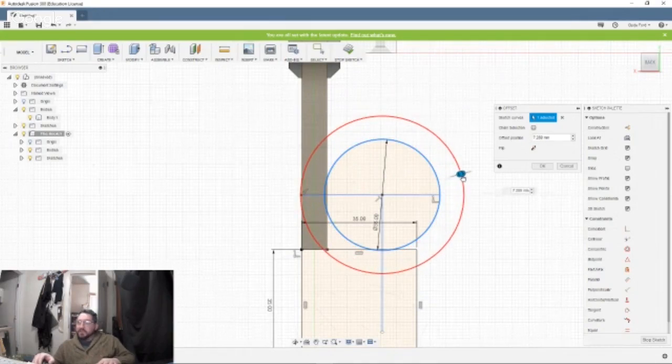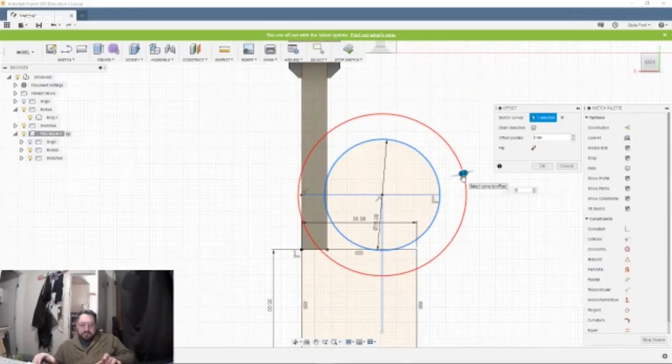I'm still learning how to use this program, and it's fantastic. I'm pretty much self-taught, but I took a lot of drafting when I was in high school and junior high school and college, so a lot of this stuff just makes sense to me. The one thing I'm having a hard time with is that I'm just starting to learn the offsets, because I started using them since it makes editing later down the line a lot easier. All you have to do now is adjust that 135 millimeter inner circle, and everything else will pan with it.